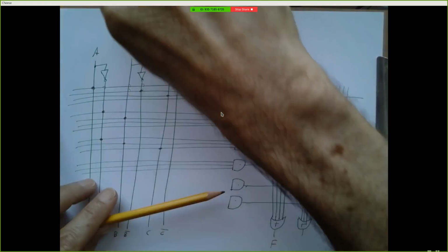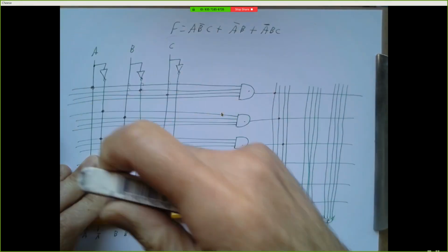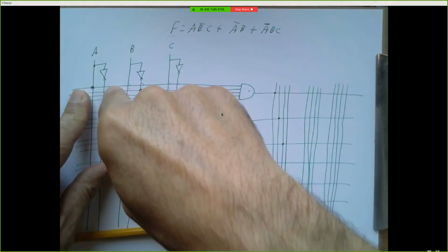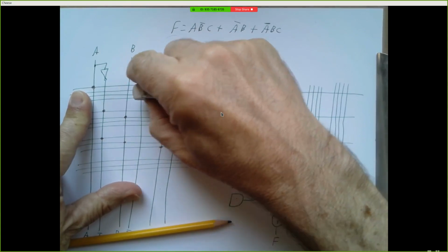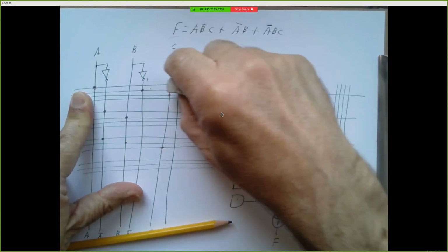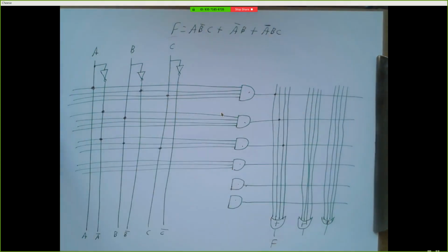And we'd come in and we'd blast a bunch of current through a set of pins that basically make this fuse melt. So we break the connection between this line and that line. And we melt all of these fuses, and this fuse, and that fuse. And we melt all the fuses except at the spots where we want a connection. And when we're done, here's the circuit that we've got, right? We've got something that implements our actual function f.